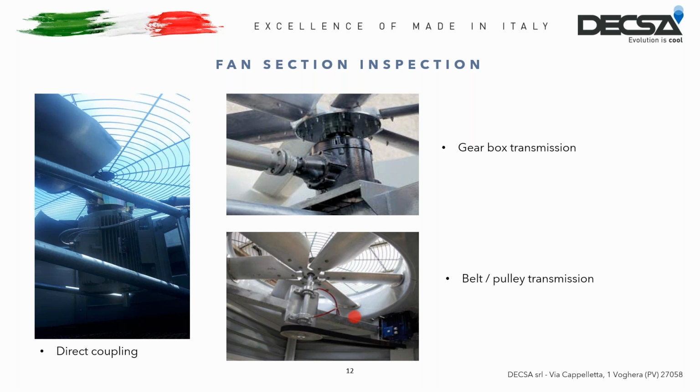Remember that too little grease will cause the bearing to dry. If the grease is too much, it will come out of the bearing seals and collect dirt on the outside, introducing it into the bearings and damaging them.